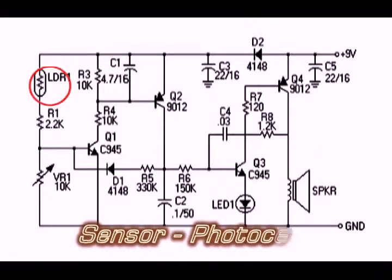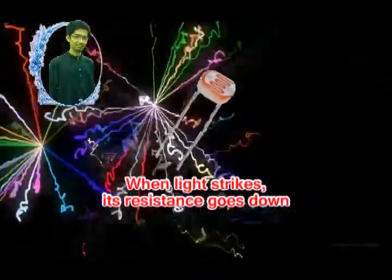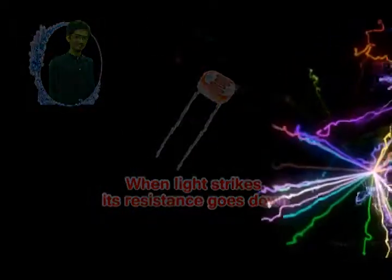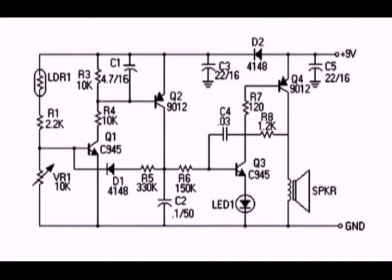LDR1, known as a photocell, acts as the sensor. The LDR has a normally very high resistance. When the light strikes the LDR, its resistance goes down to a very low value. In the circuit, LDR1 is wired in series with R1, connected as a voltage divider in conjunction with R2 and VR1, which sets the bias to the base of Q1.